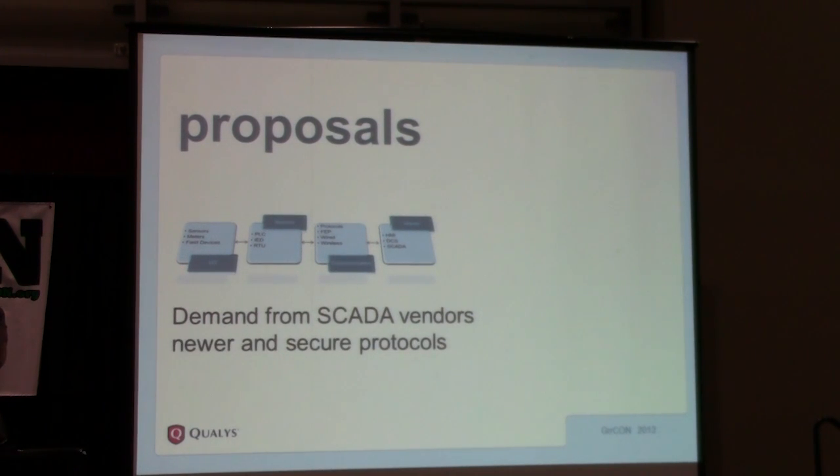Demand newer protocols from your SCADA vendors, because old protocols, as we saw, were not really meant for security, and if you are using those, you are just wide open. So demand newer protocols, and also when you get newer protocols, make sure that you are using them.